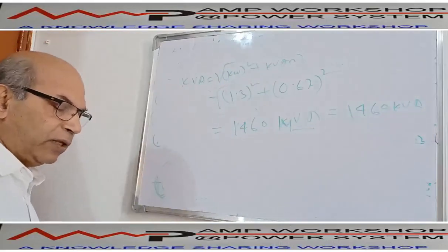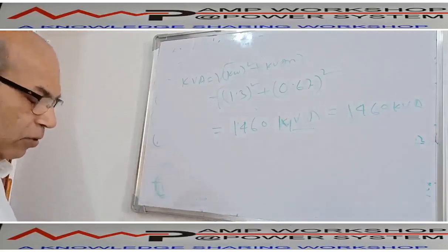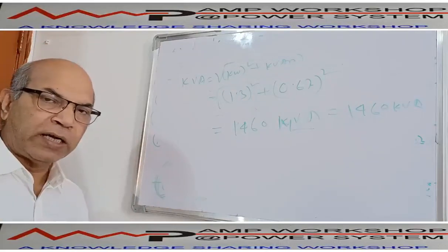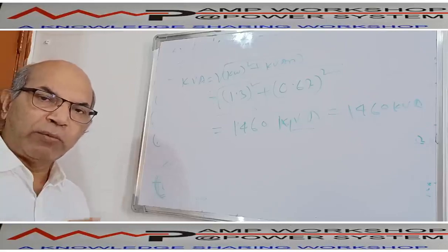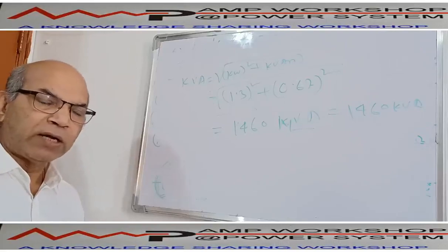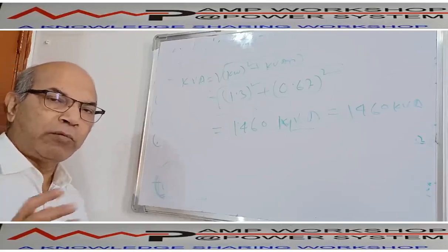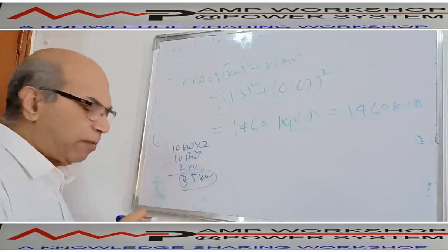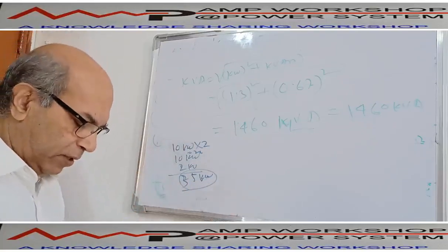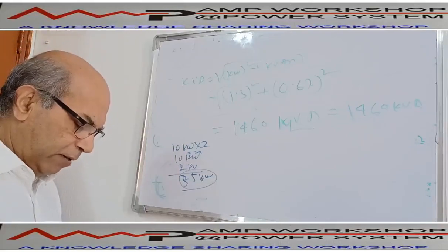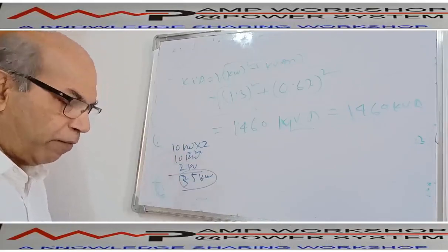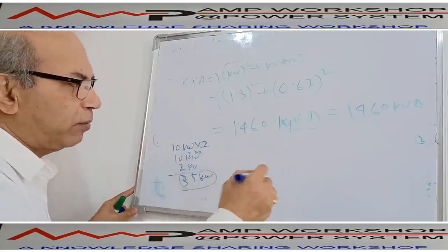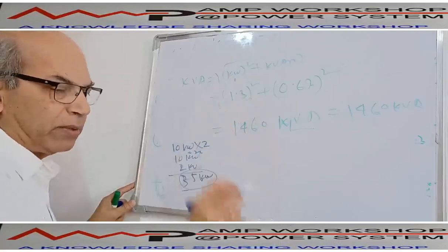Now, in addition to this, we have some other loads also. In each apartment, each tower, there will be 2 cranes, lifts will be there. Then all the 20 story corridors and common area lighting will be there. If you consider each crane, then there will be one water pump. So 35 kilowatt other load, if you consider 0.85 power factor, so 35 divided by 0.85, this is equal to 41.76.